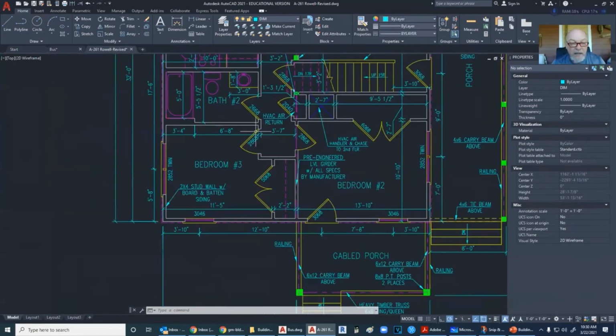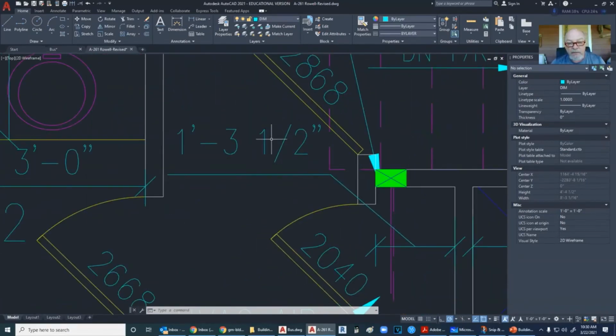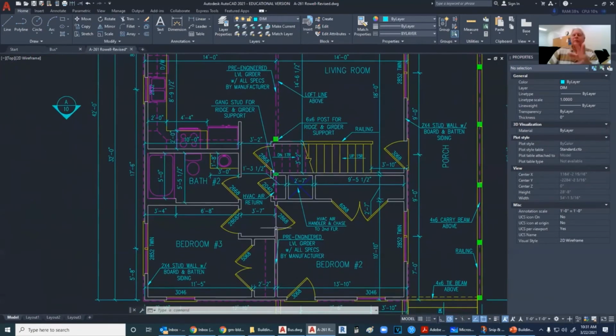But my point is, try to reduce that down to a 1/2 inch. Don't get any 8ths, don't get any 16ths, nothing. Oh yeah. Halves or wholes, that's it. Halves or wholes. So all your floor plans are designed from a framing perspective, because architecture teaches you to draw with a finished wall. So that's why you either have 5 inch or 6 inch. That's typically what we've always used. I haven't seen anybody do it this way, because you're coming at it from a more practical aspect.